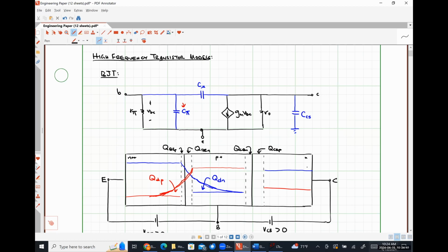Now, what the limits are on those frequencies depends on what these capacitor values are. So everything that we learned about in 335, all of those single transistor amplifiers and their characteristic input resistance, output resistance, and voltage gain, is what we call the transistor's behavior in the mid band.